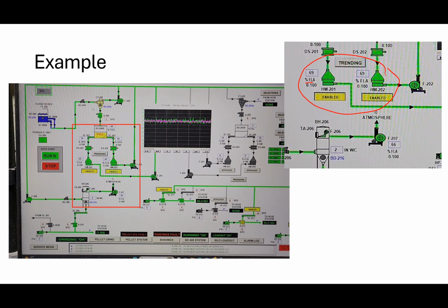All right, this guy is a hammer mill, so you can imagine he's hammering, right? He can get jammed up. If he gets jammed up, he's just going to keep, and we're going to learn why this is, but he's just going to keep jamming more and more current into it until he starts to break free. At some point, the thing's going to burn up or break something pretty badly.